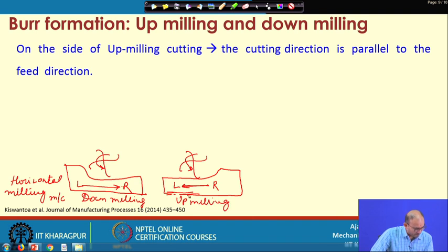Right. So, in this case, if you consider this part, why can you name this down milling? Because your cutter is moving in the downward direction with respect to the top surface of the workpiece. Now, this is the top surface and this is the machined surface by means of this milling cutter, and in this particular case, with respect to the top surface, your cutter is moving upward in this direction, that is why it is called the up milling process. This naming is in terms of the movement of the workpiece with respect to the rotation of the cutting tool.